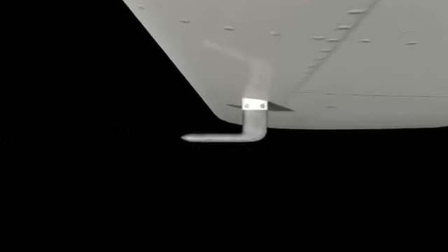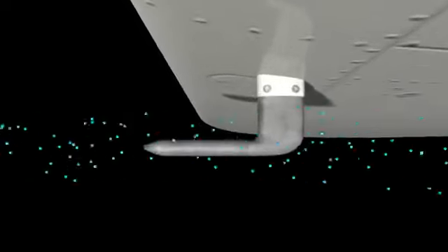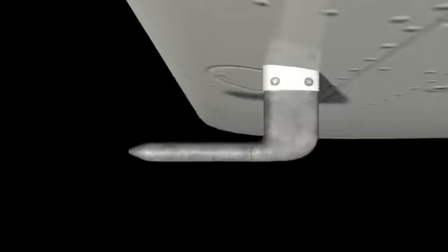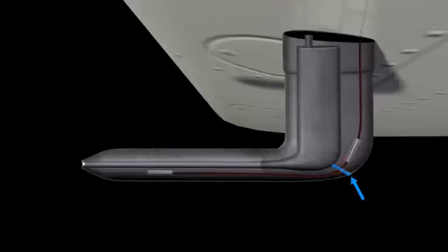In most smaller aircraft, this tube is located under the wing so it can measure the flow of air without any interference. Sometimes aircraft manufacturers will use a pitot mast instead of a tube shape, but it still functions exactly the same way. On the backside of the tube, there is a drain hole, which allows any rain or water that is collected while flying to drain out and not go into the system. Finally, the pitot tube can also be heated. This is used to prevent ice from forming on the tube, which could potentially block the hole and prevent the system from functioning correctly.